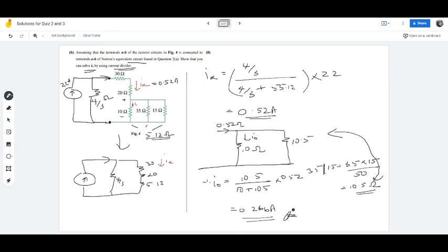You get 8 marks for that. You can see that you have to actually do current divider twice in this question. Maybe you will ask, madam, can I do it a different way? As mentioned, we need to show this bit here. As long as you show that when you get I naught, you're using current divider, how you get the value of current Ix is up to you. Maybe you want to do source transformation, then get R equivalent, and then find Is.